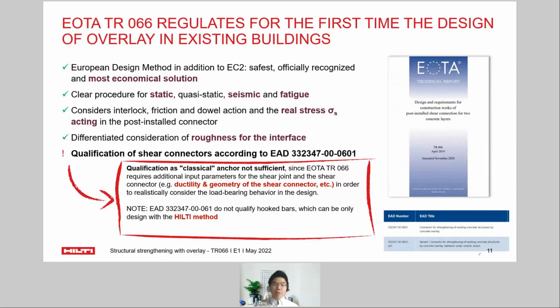It is very important to point out that the product to be designed according to this design method, TR66, has to be assessed by the European Assessment Document, EAD 332347. It is not like the normal EAD for chemical anchoring or post-installed rebar assessment.